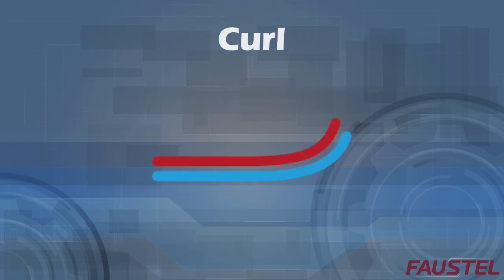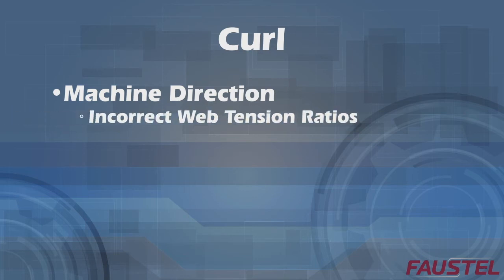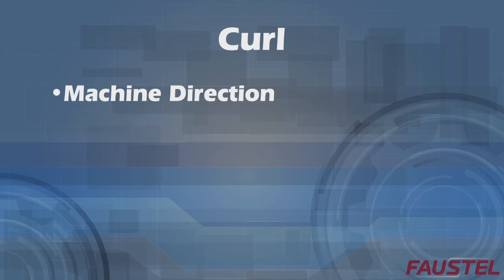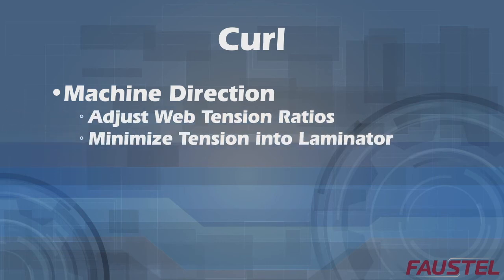There are 3 types of curl defects found in laminating. Machine direction curl can be caused by an incorrect ratio of primary to secondary web tension, or by the differential heating of the laminate components inherent in a combining nip together with different coefficients of expansion. Most of these effects can be eliminated by adjusting the tension ratio. Also, maintaining minimum tension into the laminator is always a good practice.